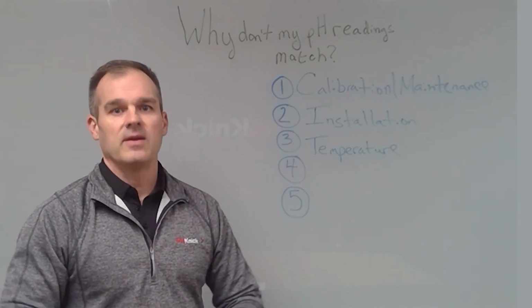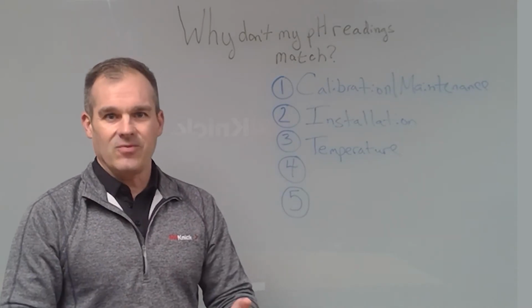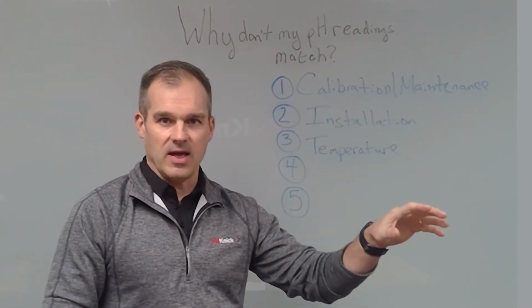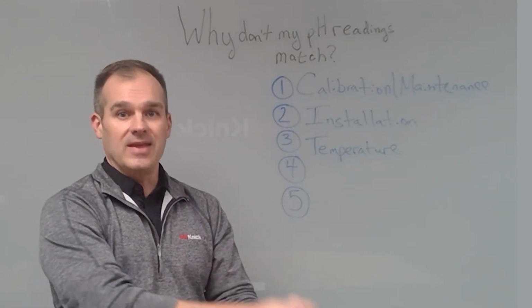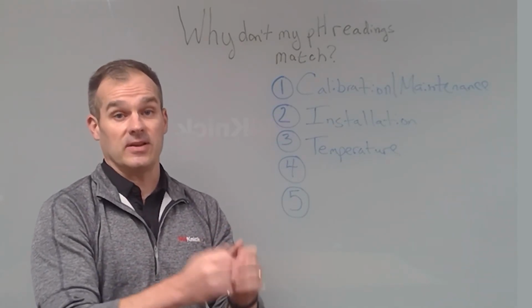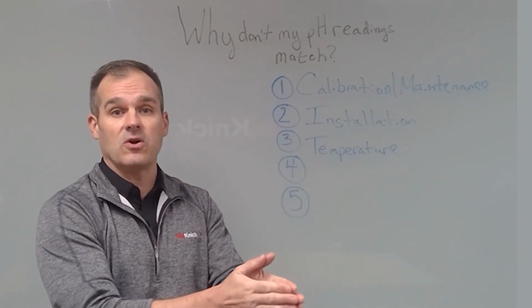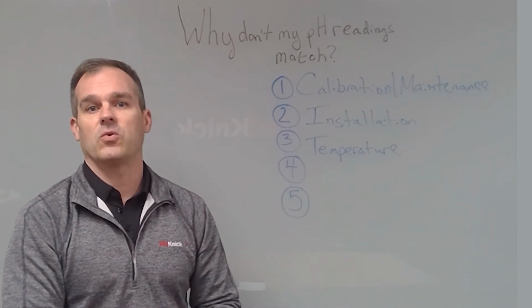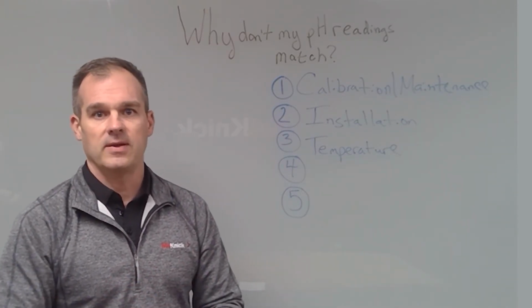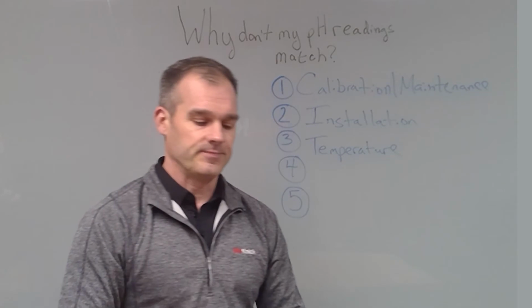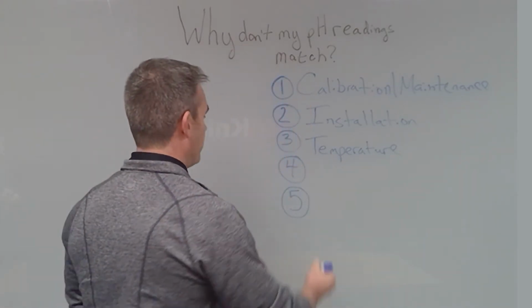Temperature is very important. If you want to get as accurate a measurement of what's happening in line, you want to take a sample nearby the installation, as close as possible to where that sensor is installed, and take that portable measurement as quickly as possible. That's the way that you can avoid that type of discrepancy. Number 4 is flow.